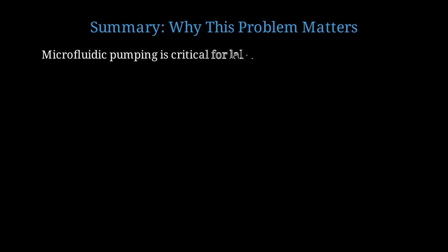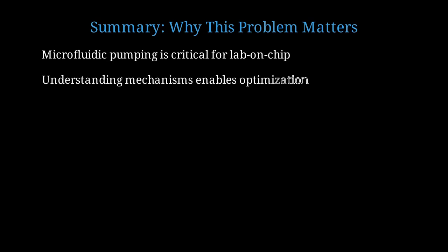Let me summarize why this problem matters beyond academic interest. Microfluidic pumping is critical for lab-on-chip devices. These devices promise point-of-care diagnostics, drug delivery, chemical synthesis. Reliable pumping is the enabling technology. Understanding the mechanisms enables optimization. If you know which effect dominates, you can design electrodes, choose fluids, select frequency to maximize performance.